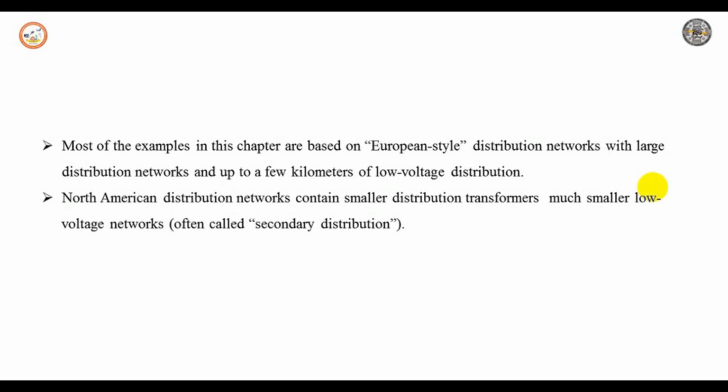It is defined in the standards by using symmetrical components. The ratio of either the negative or zero sequence components to the positive sequence components can be used to specify the percentage of unbalance. So, key point, note that here the percentage of unbalance can be specified with the ratio of either negative sequence components to positive sequence components. The most recent standards specify that the negative sequence method can be used.